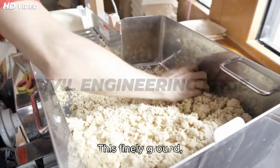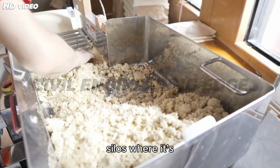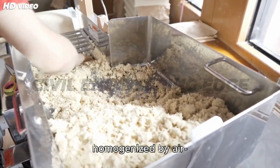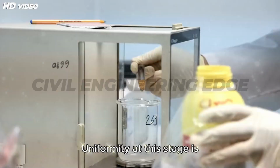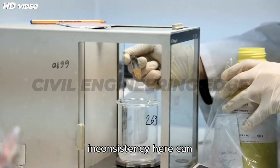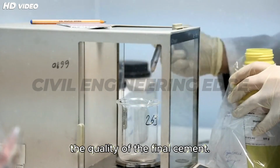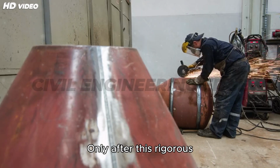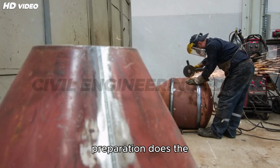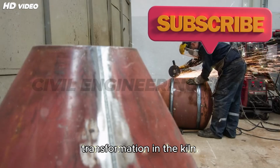This finely ground, chemically controlled raw meal is stored in mixing silos where it's homogenized by air blending or mechanical stirring. Uniformity at this stage is critical because any inconsistency here can affect the chemical reactions during heating and the quality of the final cement. Only after this rigorous preparation does the material move on to the next major stage: thermal transformation in the kiln.